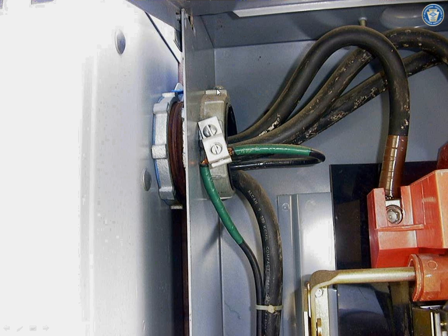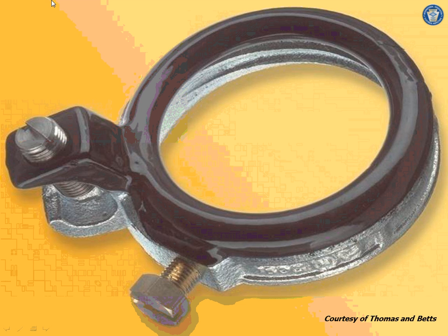Here are the most common ones. You come over here, bonding the conduit. Look how they're coming with an equipment. This is a system, a supply side bonding jumper coming in, bonding the conduit and going all the way to, I assume, the neutral part on one side. See how they lube it and they bond it. You've probably seen a few of these. Here's the notorious, the famous bonding bushing, where you can bond the conduit. This will get you an equipment bonding jumper or a supply side bonding jumper, either one of them.